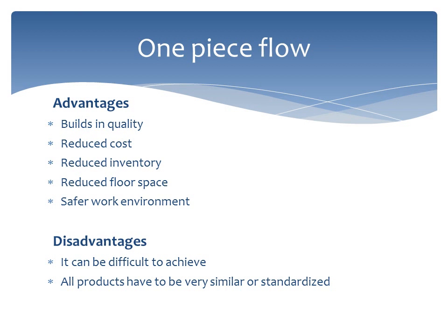Advantages: one-piece flow builds in quality. When we make one, move one, defects are detected immediately, usually in the next workstation, forcing immediate corrective action. It also improves flexibility, as one-piece flow is faster than batch and queue, and that allows us to wait longer to schedule the order and still deliver on time. There is also reduced inventory, a reduction in floor space, and a safer work environment.